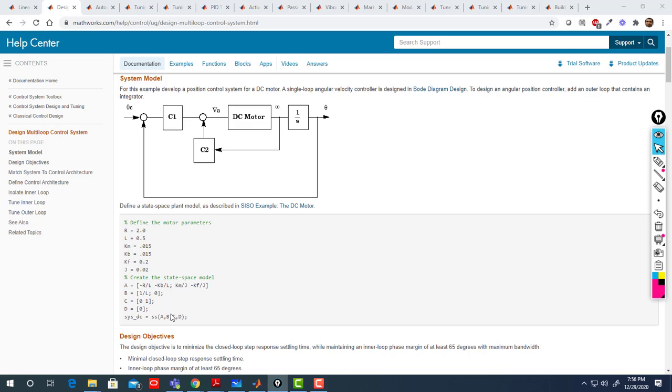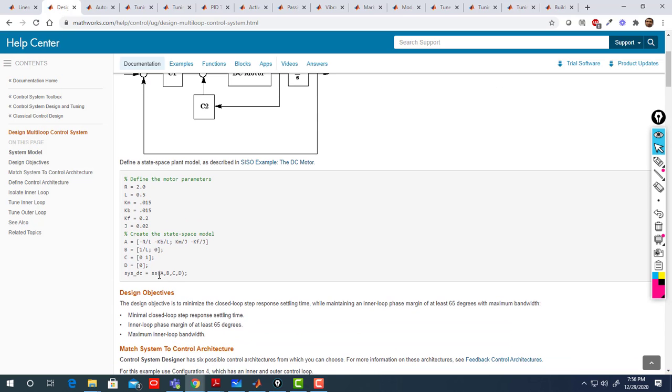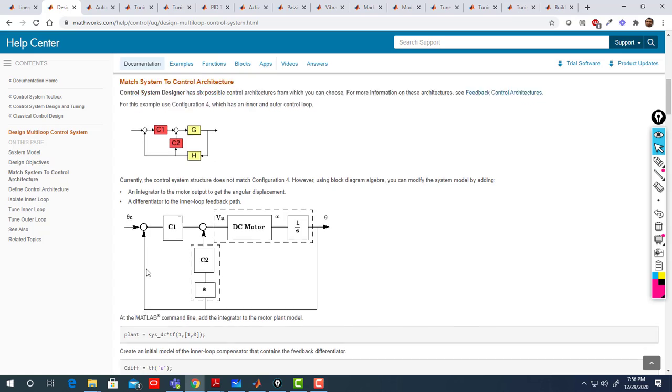If you remember the state space model from DSM, the dynamic system modeling course, we represent the system by A, B, C, D. We'll get a refresher about modeling using state space representation in our first chapter later, on state space control design. But for now, based on your DSM knowledge, the matrices A, B, C, and D are given. For now, don't worry about it. Then use ss(A,B,C,D) to get the system. You don't need to worry a lot about this.